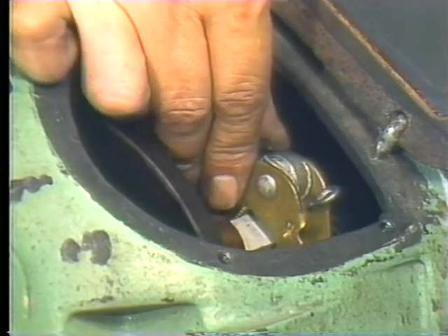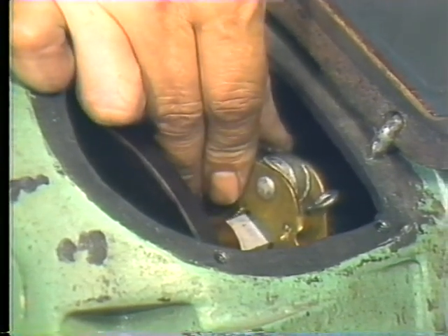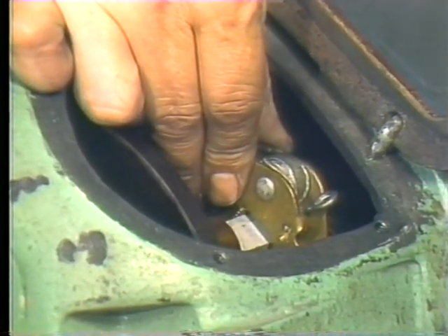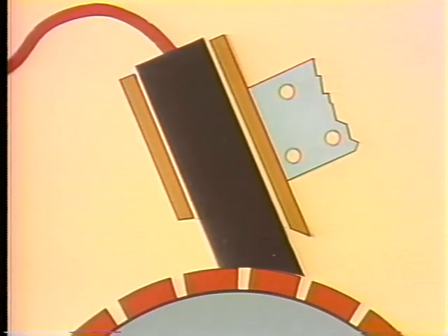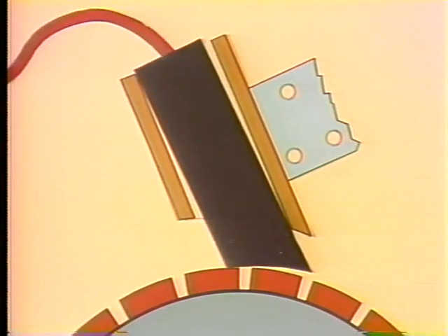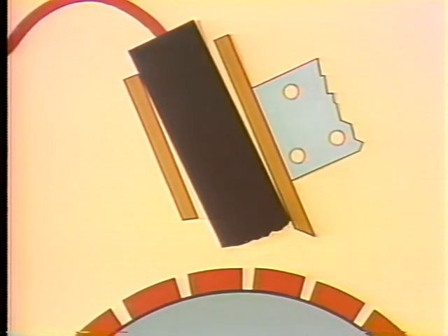Now, most brush holders can be moved, so making sure they're properly adjusted is essential. What you adjust is the amount of distance between the bottom of the holder and the surface of the commutator. Always check to see that the space between them is correct. If the rigging's too high, the brushes will chatter and make a hissing sound, or the brush could lock in the holder and break contact with the commutator. The brush could also get hung up and break off.